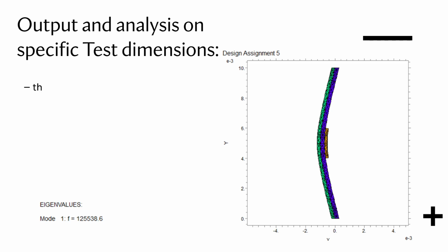The titanium layer of the piezoelectric can also be validated, as its thickness will cause reduction in the frequency of the resonator. Finally, the deposit material is free to deform, but also must be attached to the side of the quartz. There are no constraints present on it, and this is evident from the plot. Overall, the validation methods provide confidence in the accuracy of the model developed and suggest that it can be used to simulate behavior of the QCM resonator under various conditions.